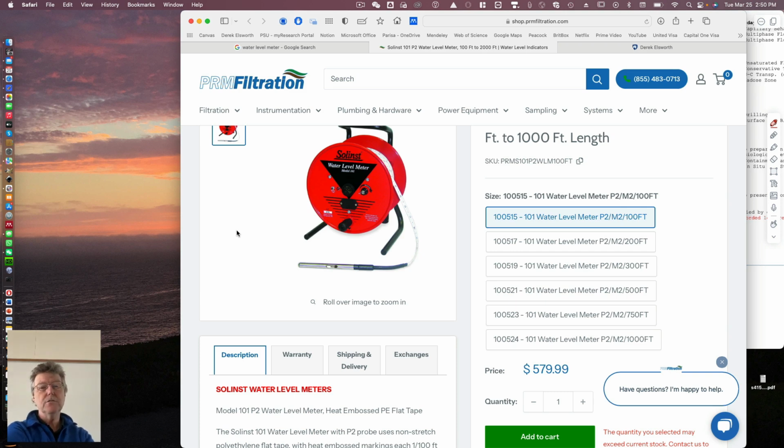Well, the way to do that is to use geophysics. And so we'll talk next time about how we can infer what's in the rest of the site by using geophysical signals of seismic velocity, electrical resistivity, radar, to be able to actually create a picture of the site between the boreholes, and then use the boreholes to calibrate it against places where you know exactly what is in place. And so if you know what the geophysical signals are at those locations, you can ground truth your boreholes against your predictions from the geophysics. So that's what we're talking about. And that will be, sadly, I know, your last class.